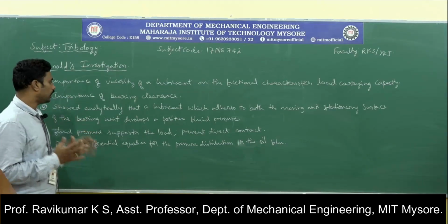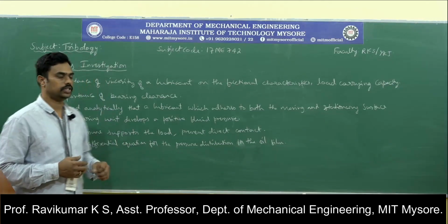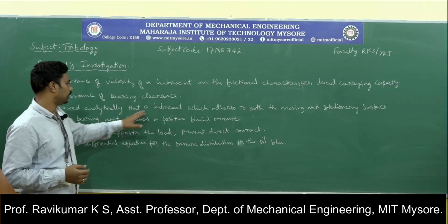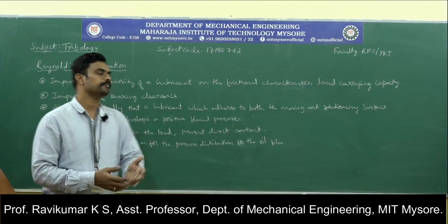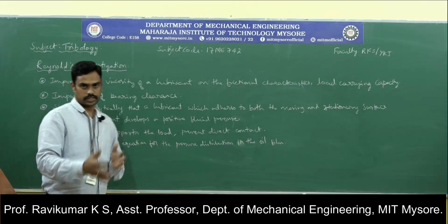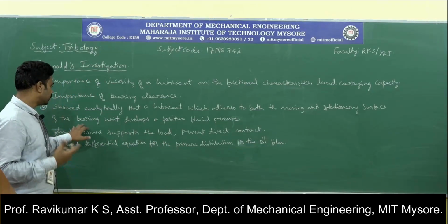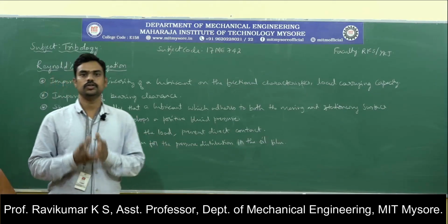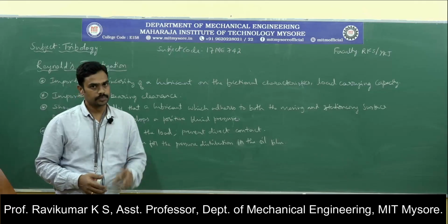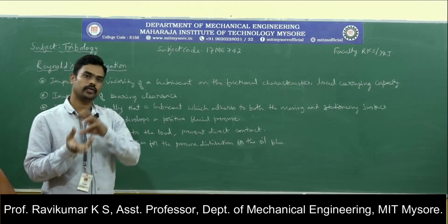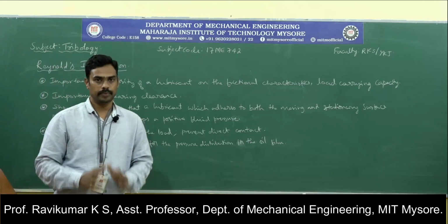Then he showed analytically, which means with the help of some equations, that the lubricant which adheres to the surfaces of both the moving and the stationary parts, that is the journal as well as the bearing surface, develops a positive fluid pressure. So Tower conducted certain experiments and concluded that there will be a pressure distribution in the oil film between the journal and the bearing.